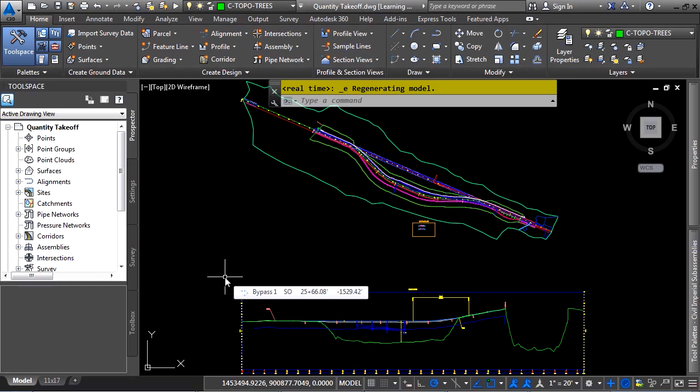When pay items are assigned to AutoCAD Civil 3D code set styles, a corridor object is automatically assigned those specified pay items, as well as any Civil 3D pipe network parts list that you associate pay items to. Those pipes and structures will automatically be tagged as well.